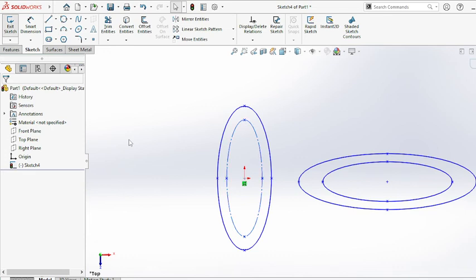See, after that we can go here, partial ellipse. Partial ellipse means the ellipse arc command, you know, ellipse arc in AutoCAD. You can specify the angle. So I don't need a full ellipse. I need the ellipse from some angle to some angle only. That is called ellipse arc. Here partial ellipse is also the same as ellipse arc. So we can go to the partial ellipse.